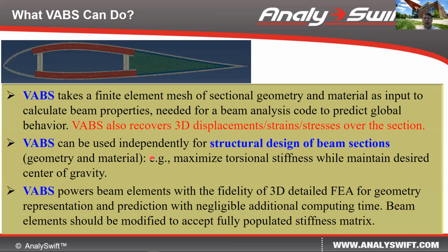VABS can also be used along with a finite element beam model to power the conventional beam elements with the fidelity of 3D detailed FEA, for not only the prediction but also geometry representation, with negligible additional computing time compared to the traditional beam theory.